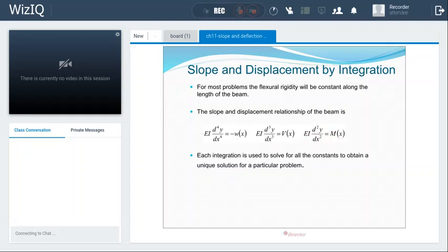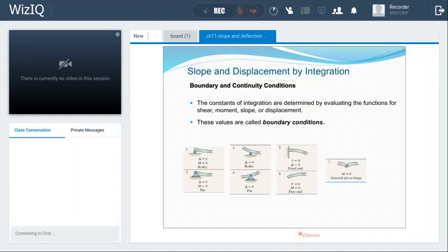So this is just a simple solution of the differential equations by applying the boundary conditions, and you will see how we can calculate the values of slope and deflection. You can see here, we should know what are those boundary conditions at every support, because support is not allowing the beam to move from that point. That means it is providing an obstacle for movement and also for rotation in some cases.